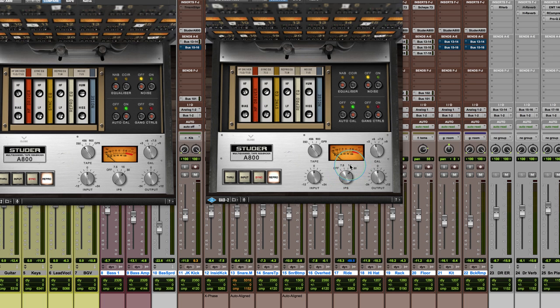On this, you get a little boost on the high frequencies, around 15, 16K, and a boost on the low end, which a lot of people like, which is why it comes up as the default. At 7.5, you lose more high frequency, but you get even more low end, so this gives you the warmest sound. The different tapes handle different amounts of gain, so this is a way of calibrating how much magnetic field strength is being applied to the tape.